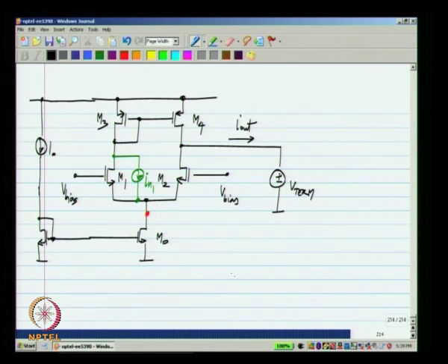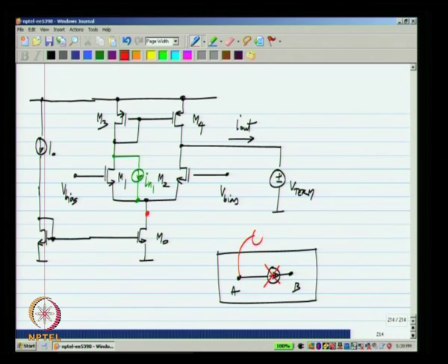In any circuit, let us say I have a current source between A and B, I can replace that with a series combination of two current sources of exactly the same value. So, let me call this Ix. This will be Ix and that will also be Ix. Okay. Clearly, KCL is satisfied here and also nothing has changed at nodes A and B. So, this is fine.